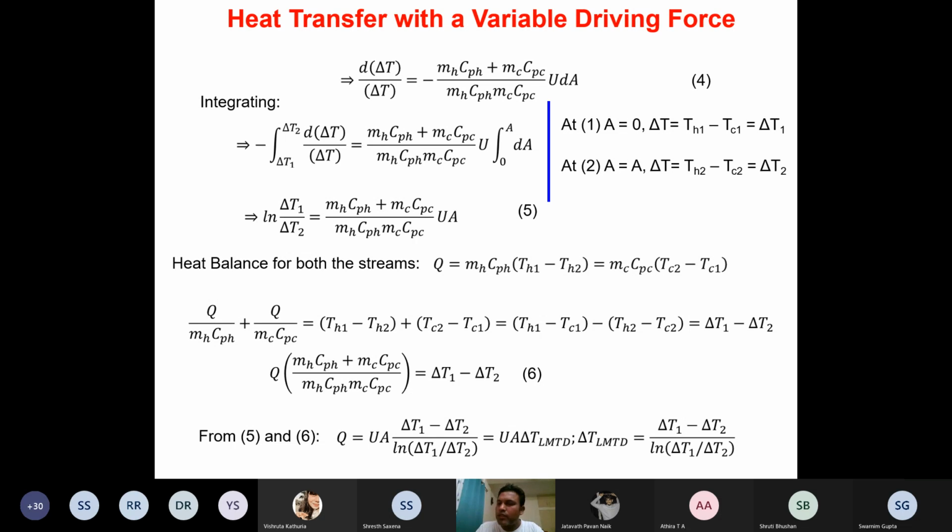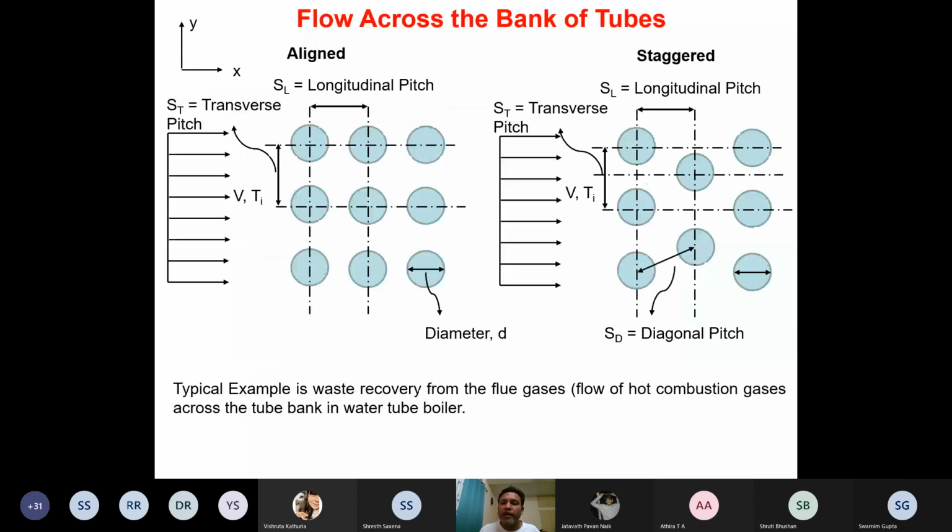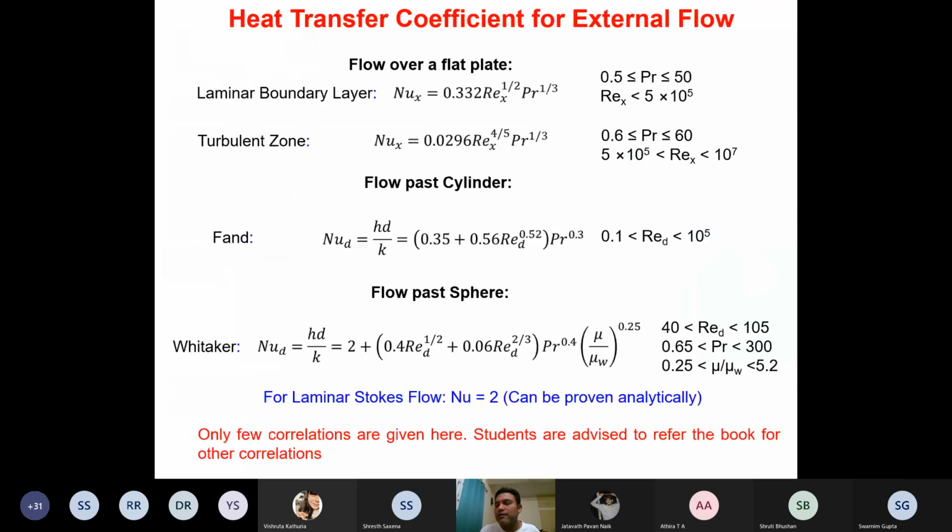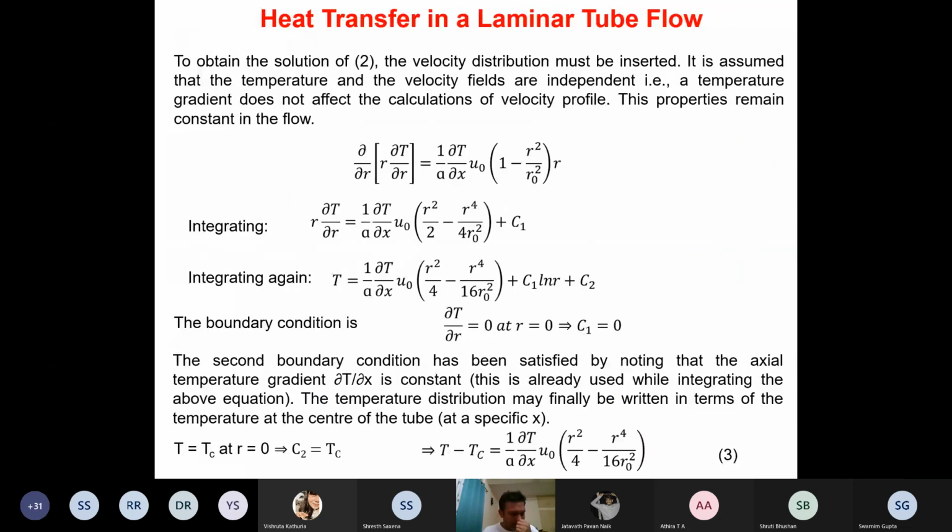Before the minor one, we started looking at forced convection. We started with the argument that in forced convection, in order to solve the heat transfer problem, first we have to solve the momentum transfer problem, and then the velocity distribution has to be put into the energy balance, and finally the energy balance has to be solved. So even though the modeling can be easily done, solving the model computationally is difficult, isn't it? That is what we have argued.